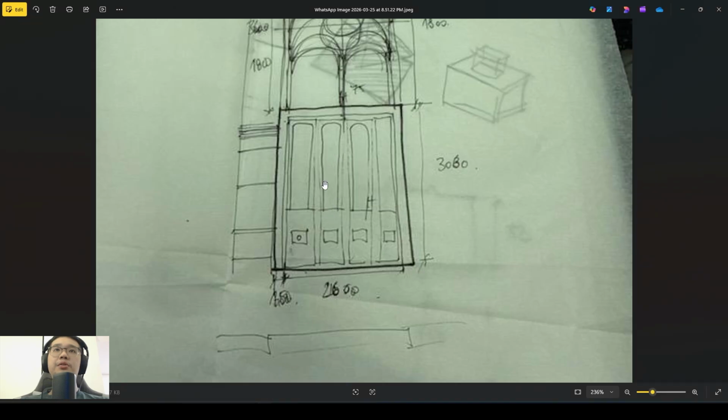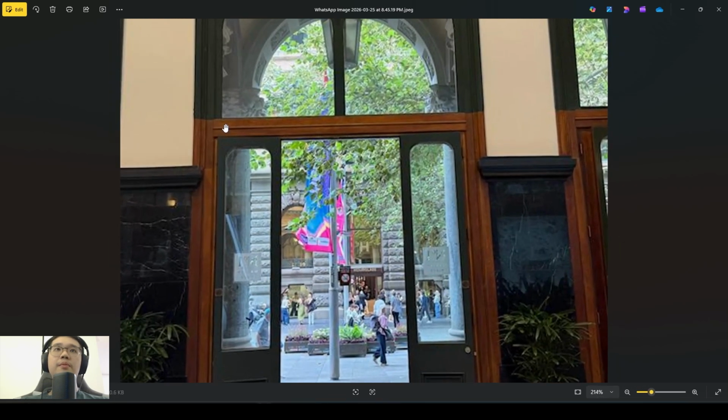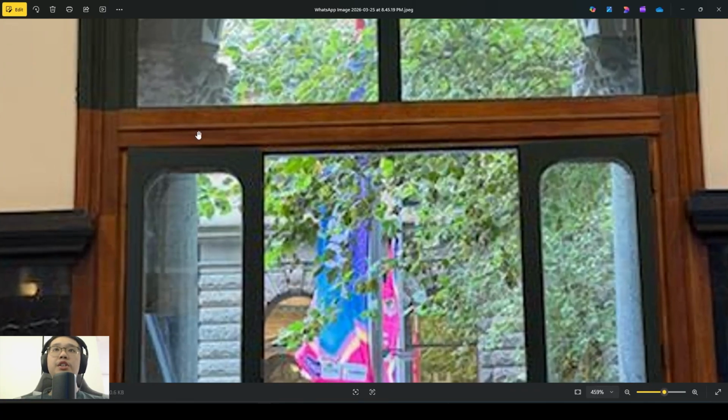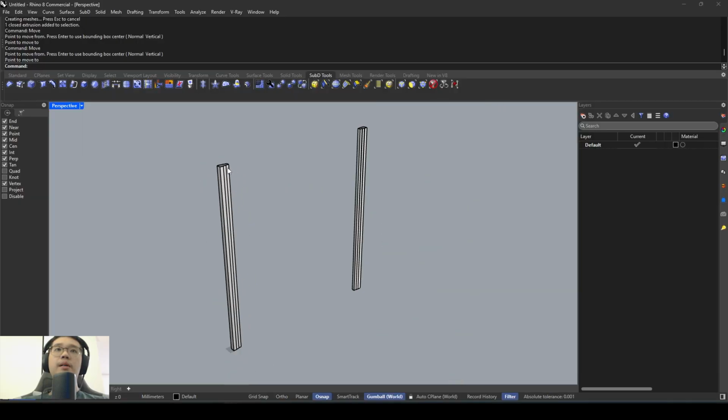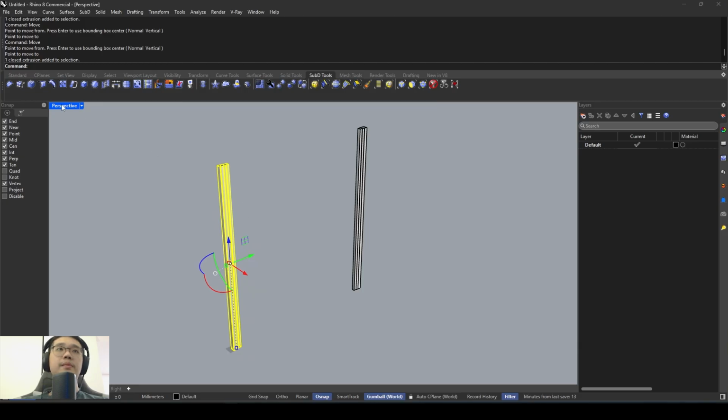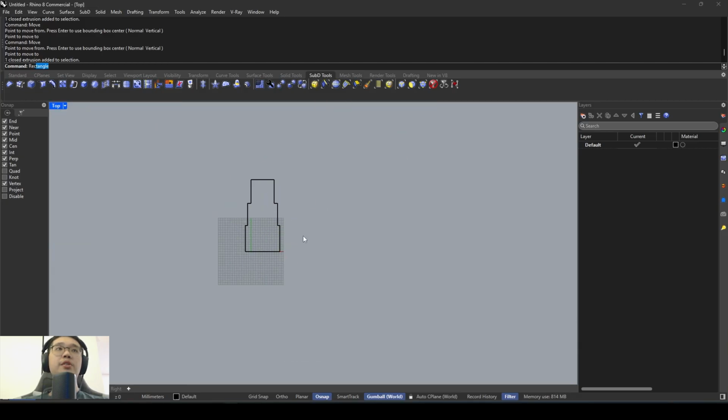And the next step here is to model the top frame, the head of the window, which looks like it has a different molding shape. So I'll go back into Rhino. What I'll do is create another shape here, just right next to it. I'll command rectangle, scale 1D, to scale the box down to 50 mil, and the width was 150.